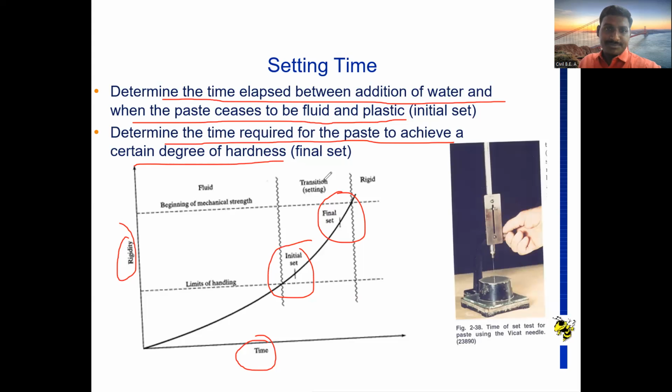When the concrete becomes rigid, it means it is no longer workable, and that is the plastic limit, so a rigid paste will be formed. Up to the point the rigid paste forms, we note the time, and that is the final setting time. This graph is shown in the IS code also, where the setting time properties of the cement are given.